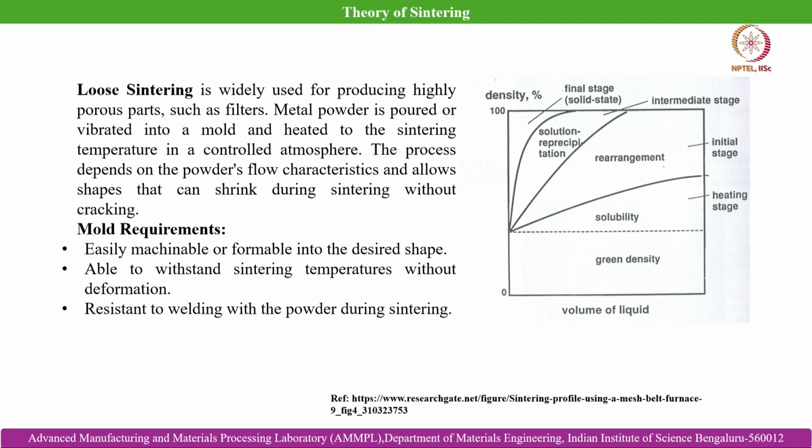So, the mold requirements are that it is easily machinable or formable into the desired shape and able to withstand sintering temperatures without deformation, and it must be resistant to welding with the powder during sintering. So, these are basically the primary requirements of the mold.